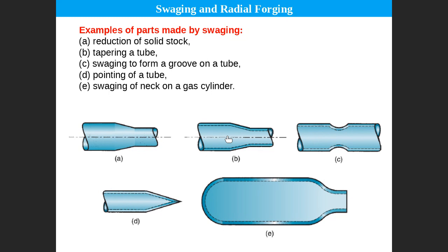So how can we solve the problem in a hollow cross section? How can we hammer the hollow cross section without destroying the internal surface? Actually, simply I tell you that we add an internal mandrel. We add what we call an internal mandrel. What is the internal mandrel? Actually, they put sand. Do you know the sand?